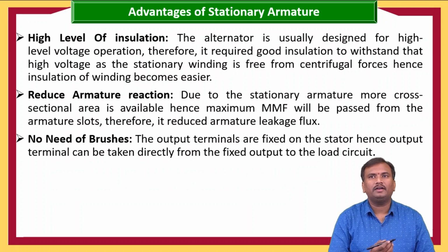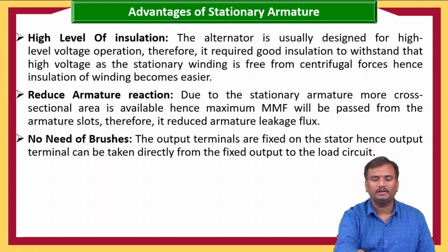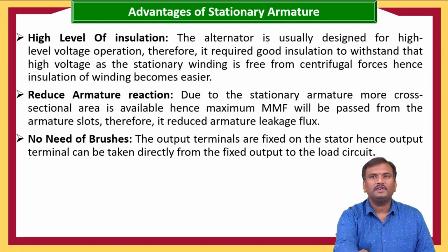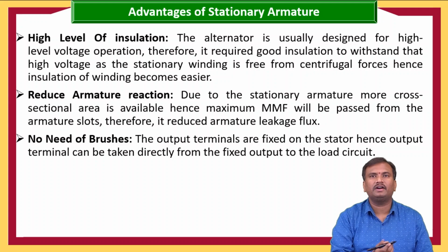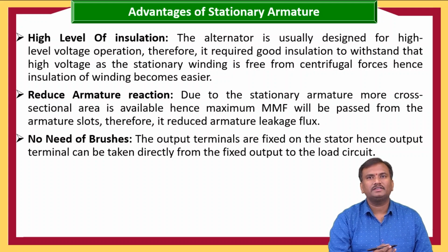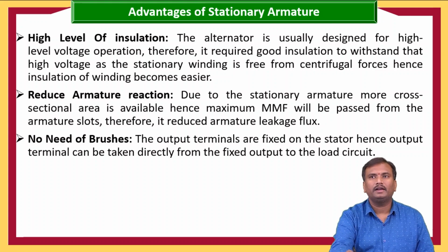And here are the advantages of having a stationary armature. The first advantage is a high level of insulation. The alternator is usually designed for high voltage operation. Generally, whatever generating stations we have generate high voltage, which requires a good insulation to withstand the high voltage.